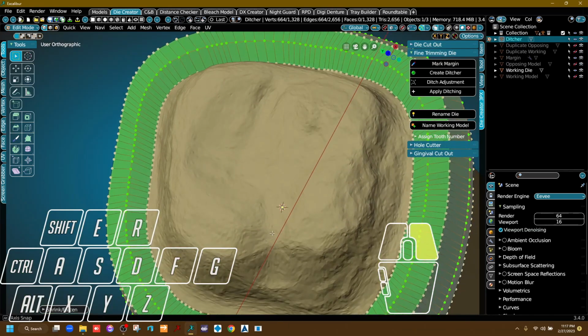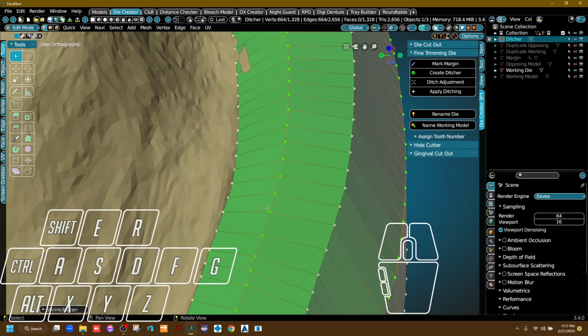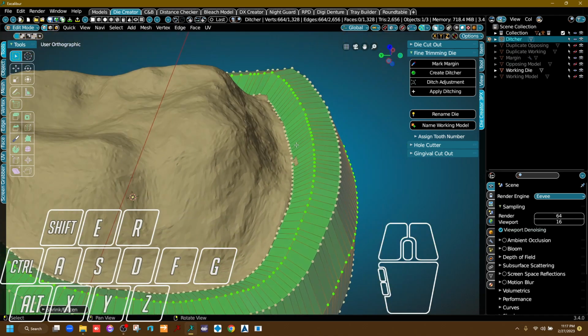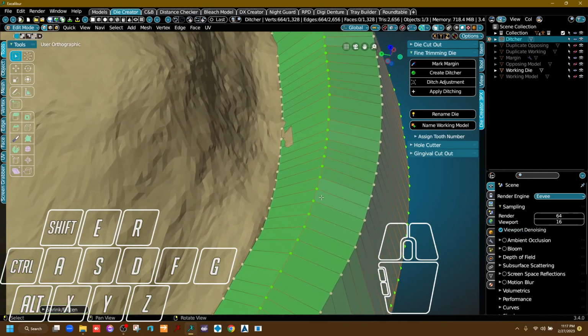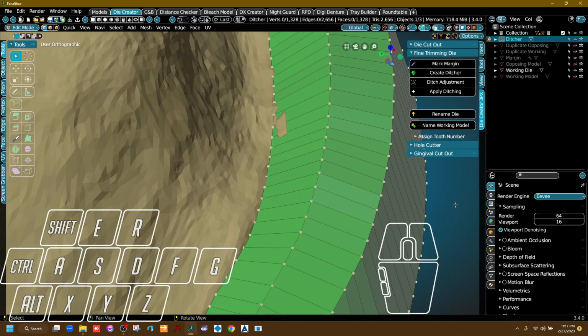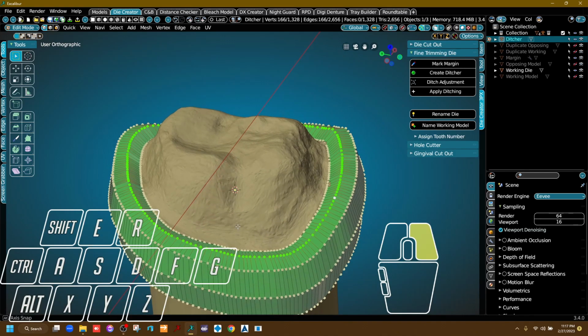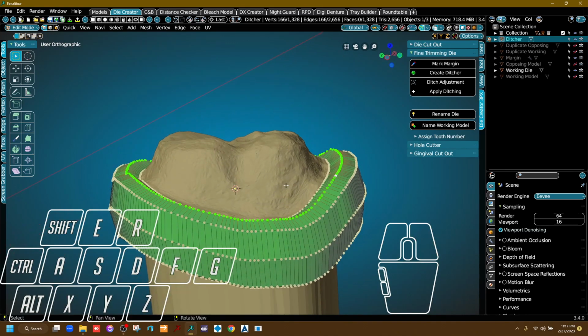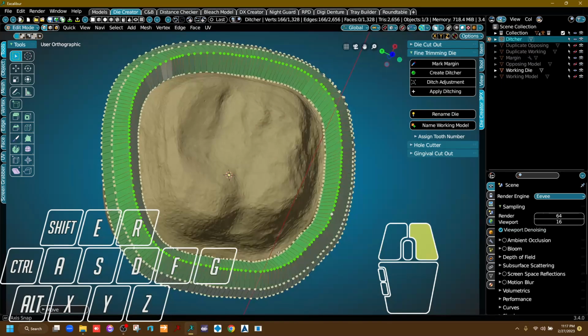One solution to this is to click and select just these points on the top, and then you can edit those points. That way you definitely have everything cut that you wanted to cut. So what I can do is click off of this so no points are selected. Hold down the Alt key and click specifically not on one of these points, but on the line connecting the two of them together. And that should highlight all the points on the top specifically. From there, I can grab these points with G and move my mouse up. And that can usually get rid of these.